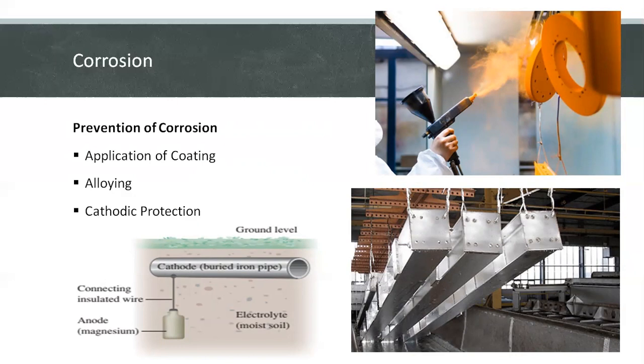In addition, a new technology is now being developed to create surface alloys. That is, instead of forming a metal alloy such as stainless steel, which has the same composition throughout, cheaper carbon steel is treated by ion bombardment to produce a thin layer of stainless steel or other desirable alloy on the surface. In this process, a plasma or ion gas of the alloying ions is formed at high temperatures and is then directed onto the surface of the metal.